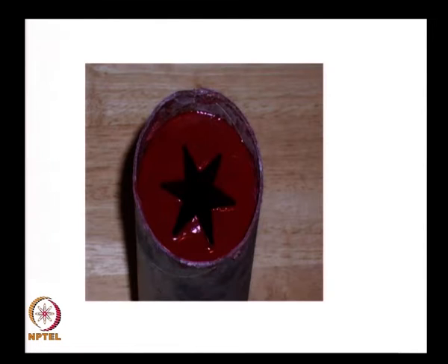Having said that, now I show a picture of this grain. Instead of having the grain which was circular on the inside, I sort of wrinkle the surface such that I have something like a star shape, and this star shape is happening all along the grain surface. And now for this, what is going to happen? The inner burning surface area Sb is going to be much larger. In other words, Sb is going to be the perimeter of this particular star multiplied by the length along the grain, and that is going to be the initial burning surface area. Therefore the pressure will be much higher, and the thrust will be much higher compared to what it would have been had it been pi d naught.